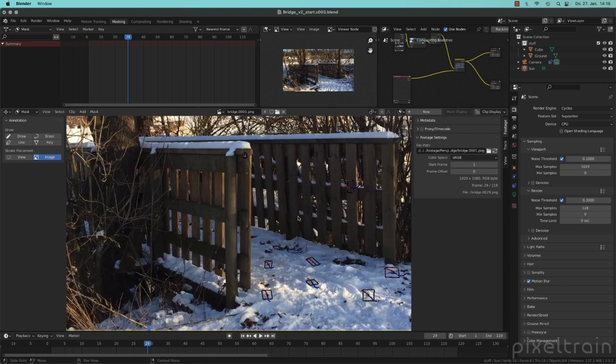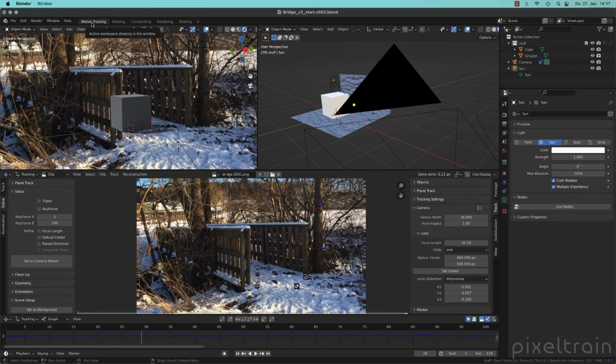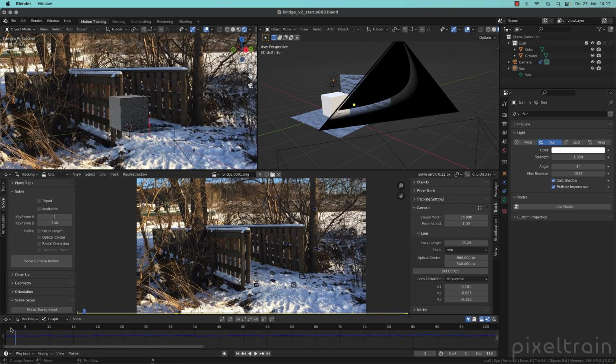Now, let's talk a little bit about how to rotoscope. This rotoscoping process is the same rotoscoping process as you have in applications like Nuke or Fusion or After Effects. It's really the same rules. Don't try to rotoscope everything in one big chunk. Try to split it into easy static objects. Then you can combine these elements to masks, and then you use the mask in the compositing process. So absolutely the same thing. So if you want to dive into rotoscoping, all these tutorials are good, not only the Blender ones. But the first thing I normally do is I try to understand where I need my rotoscope, because rotoscoping always takes time and I don't want to do more work than I should do. Let's go first back to the motion tracking world here and look through the camera and try to understand what we need.